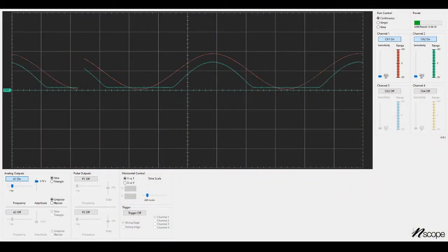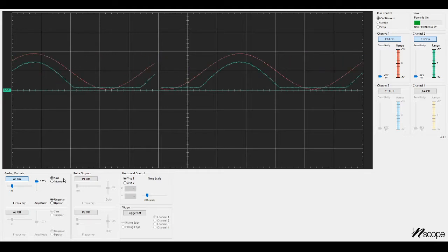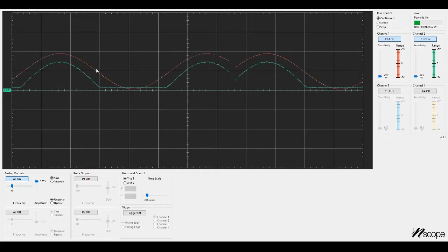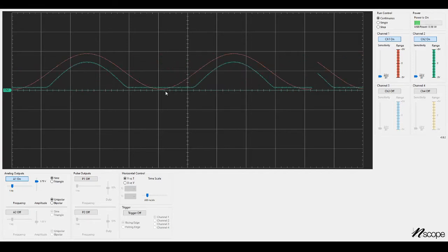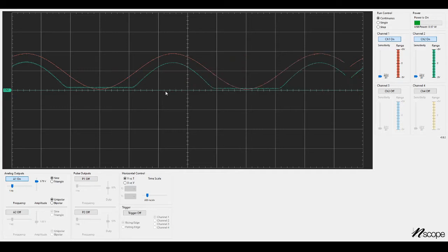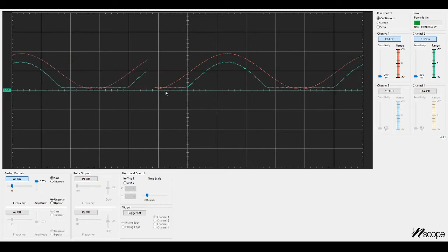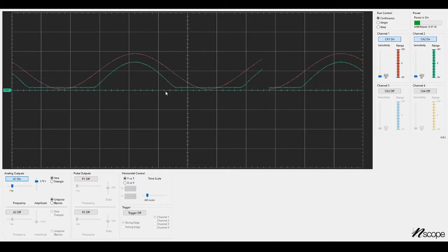And what do we know about these voltages? So the red line, that's the sine wave coming from A1 going to the LED, pretty straightforward. The green line, this is the voltage from the phototransistor circuit. We can see there's a slight bit of sine wave on top of it. I'm going to cover it with my hand. Okay, so now the only light that can hit the phototransistor is coming from the LED. That little sine wave went away. So the lights in my room are actually flickering a little bit. That's probably because I have these cheap LEDs to illuminate my camera rig here, and they're flickering at maybe 60 or 100 hertz.